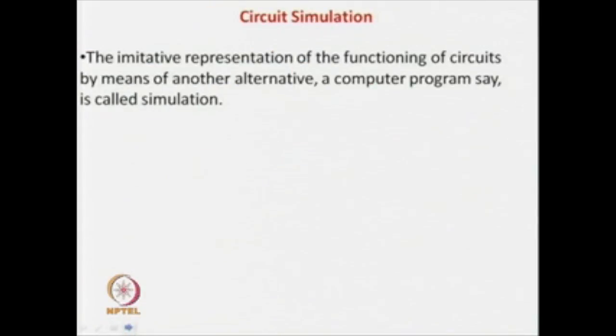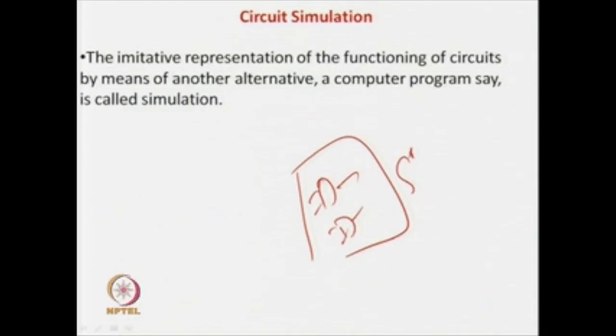We have seen test pattern generation by random patterns. What do we have to do? We have to take the circuit, give some input and get the output. But the circuit is not yet fabricated. We are finding out which patterns have to be applied when the circuit is fabricated. So, all this test generation activity is done while the circuit is being designed. Fabrication has not been done, so we do not have the fabricated version of the circuit. We have the circuit in soft copy, say in a program or some other manner, and then you have to find out which patterns to apply.